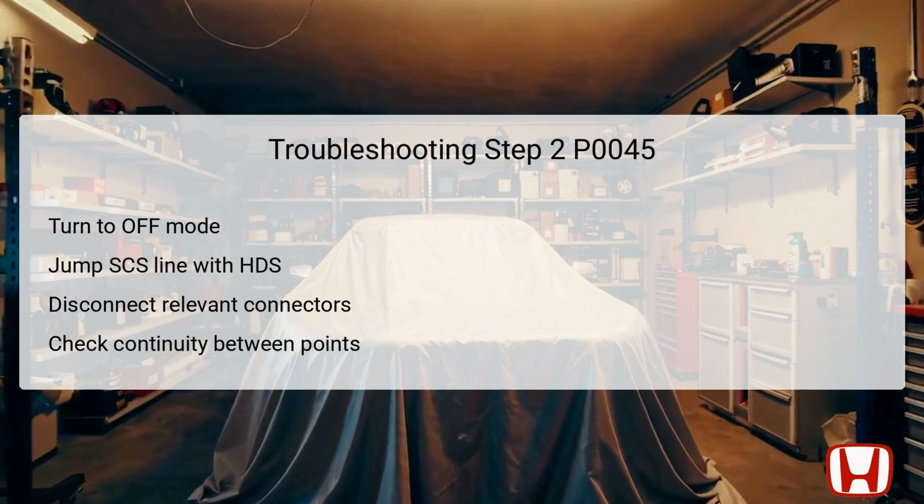Following this, disconnect the Turbocharger 5P connector as well as the PCM connector E, which is an 80-pin connector crucial for communication with the engine management system. Now, you will check the continuity between test points, specifically between the Turbocharger 5P connector and body ground.